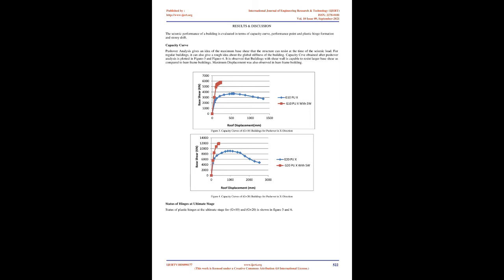All buildings are designed as per IS 456:2000 for adequate main and shear reinforcements, corresponding to the ultimate moment capacity level. Flexural plastic hinges will be developed along with the predicted values of ultimate moment capacity when there is no prior failure in shear. Therefore, there is no need for shear hinge modeling, as it is obvious for a code-designed building to fail in flexure and not in shear.